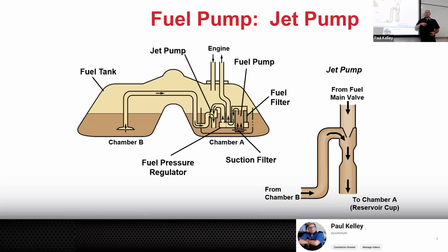So it'd be better to clean the tank extensively and do the fuel pump in there, and that's going to be pricey. It just is what it is. And then again, most of these are going to be jet pumps, so they don't really like this type of suction pipe, but sometimes they may need to. It's better if it's fully submerged.